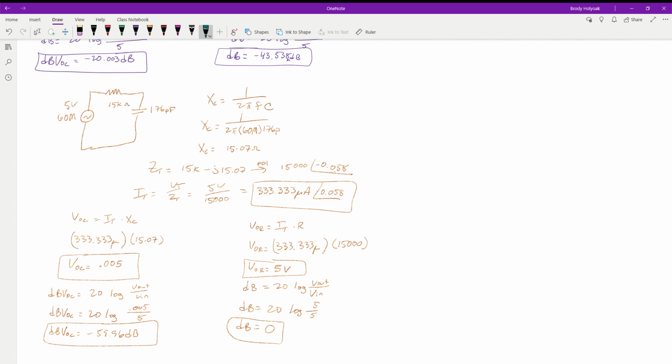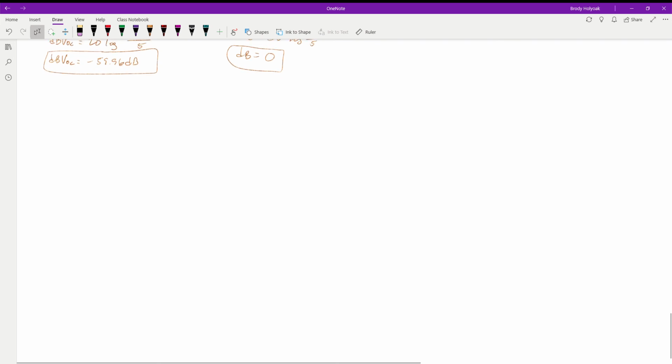And I'm going to do this in the magenta pink color next to it. So what we want to know is, what is our critical frequency? How do we find it? Actually, I'm just going to put this below it. What is our critical frequency? At what point do we call this a filter? And what is this frequency that we're going to label this as? So remember, at our critical frequency is when our reactance equals the resistance.